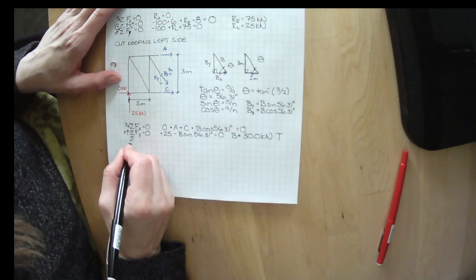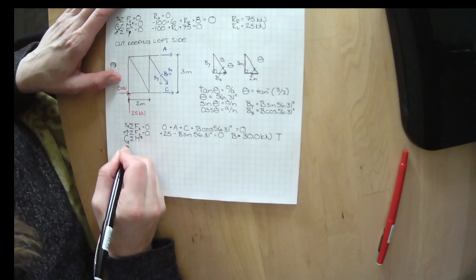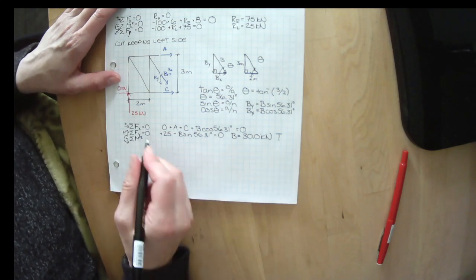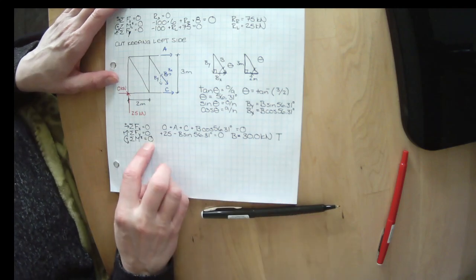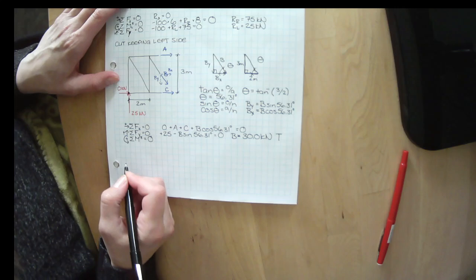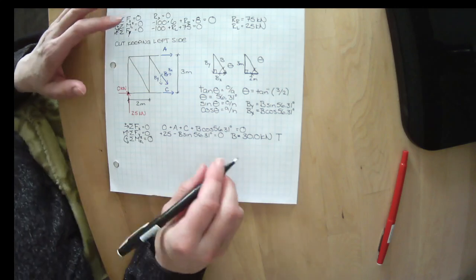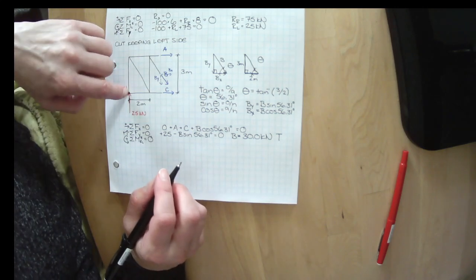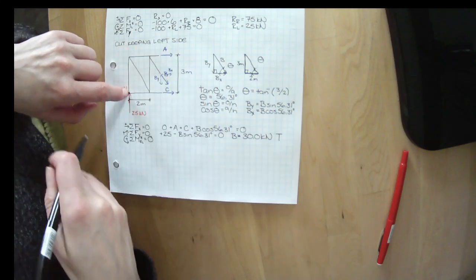Now let's sum the moments about the z-axis where everything spinning in that direction is positive. We want to know what it takes for this to be in equilibrium, for the sum of those moments to be 0. And I'm going to pick that point right there. I'm going to pick reaction L, or my left reaction, to spin about. So I'm going to imagine that the thumbtack is right here, causing this thing to spin.